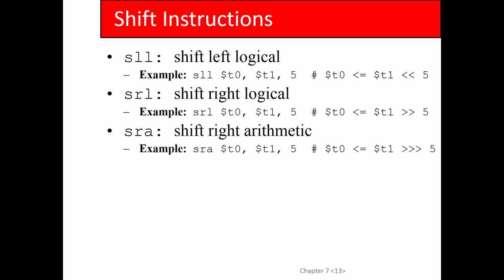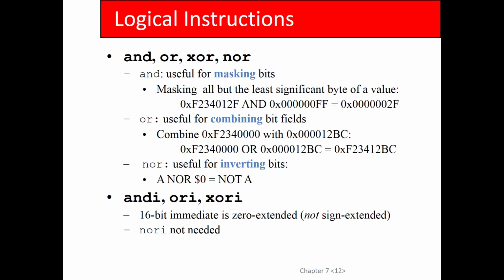But the idea there is, if I do an AND instruction, that would mean I want to take two register values out of the register file, do a bitwise AND, and then store the result back to the register file, right? So I would be doing that if I were doing bit masking, like if I wanted to zero out parts of a register but not the whole register, for instance.